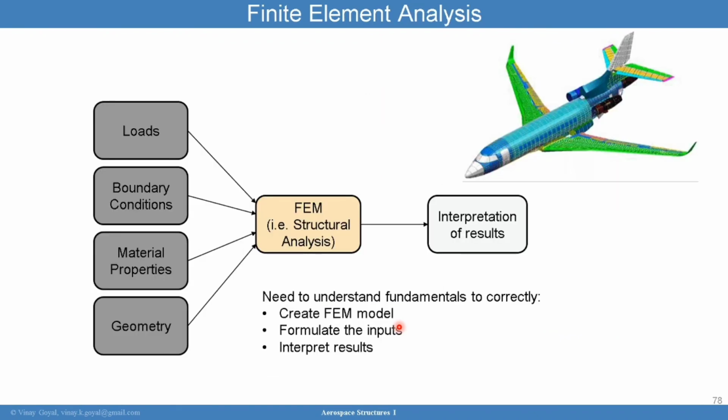If I go a layer deeper now into what's going on, this is an aircraft finite element model, and it probably has over 100,000 elements, although some models can have up to a million elements. In this case, what you see here is a CAD model was provided, and a mesh was created, meaning that we have divided and discretized the domain into subdomains.